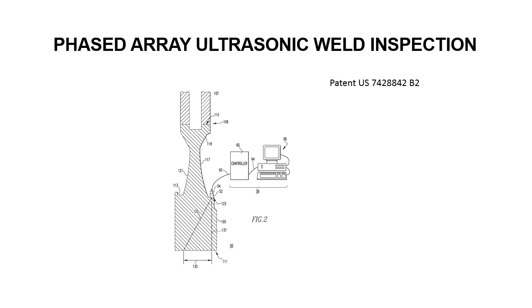This method is an advanced NDT method that is used to detect component failures, i.e. cracks or flaws, and thereby determine component quality. Due to the possibility to control parameters such as beam angle and focal distance, this method is very efficient regarding defect detection and speed of testing.